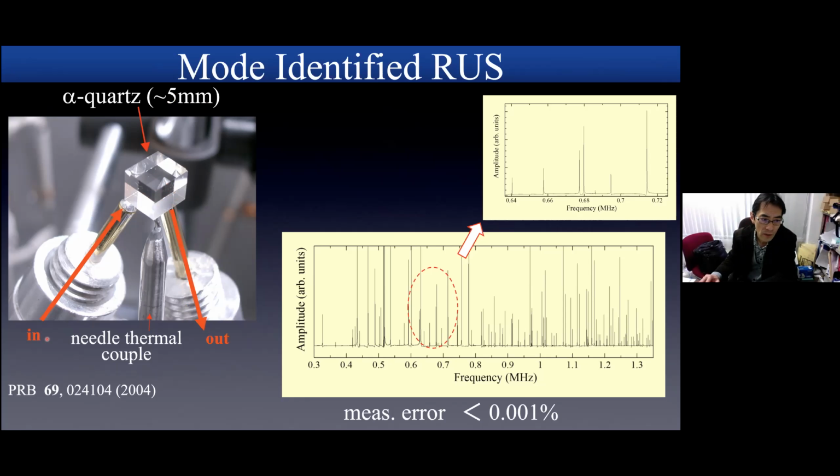By sweeping the frequency of the driving input, and then measuring the amplitude of the detected signal, we can detect many resonant frequencies like this. All resonant frequencies are affected by the independent elastic constants, but the contribution of each elastic constant is different for each mode.